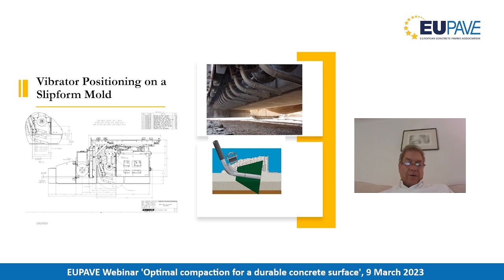So you can lower if you're paving a 600mm slab, you can lower the vibrator to 300 to give you all the consolidation you want. If you're paving a 220mm road slab, you can raise the vibrator, and if you're paving over blockouts, you can raise it to above the roof of the mould.